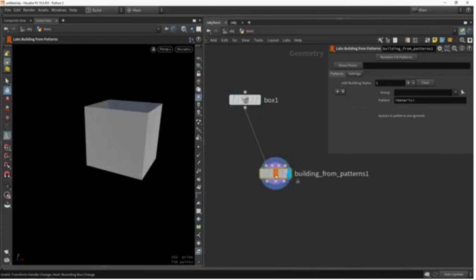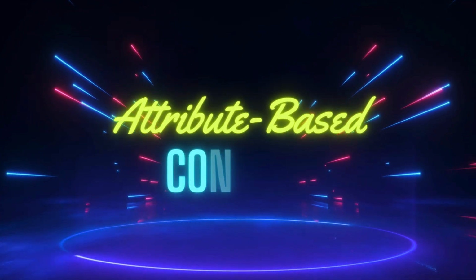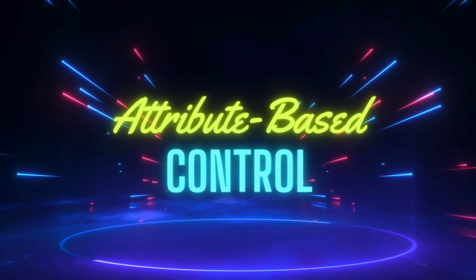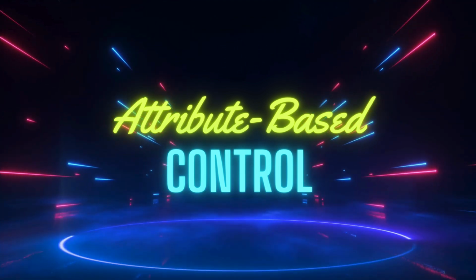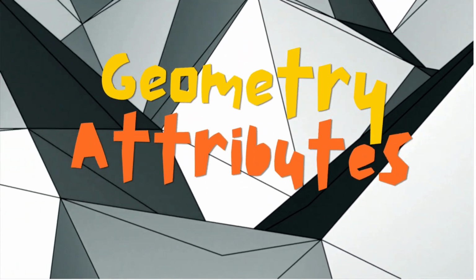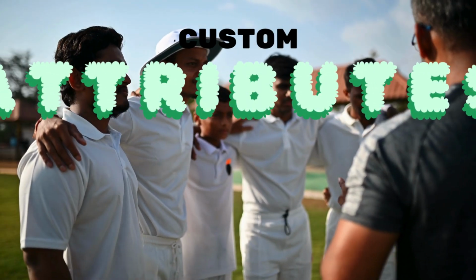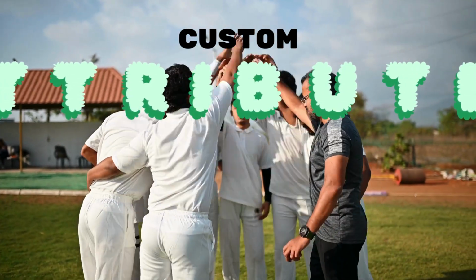The next aspect of procedural workflows is attribute-based control. Attributes are a key part of Houdini's procedural system. They allow you to control almost every aspect of the workflow. There are two types of attribute-based controls that you need to focus on initially. That's geometry attributes, which are position, normals, and UV coordinates. And then you have custom attributes defined by the user for specific tasks such as density or temperature. These attributes can be manipulated mathematically, providing fine control over geometry, simulations, and effects.